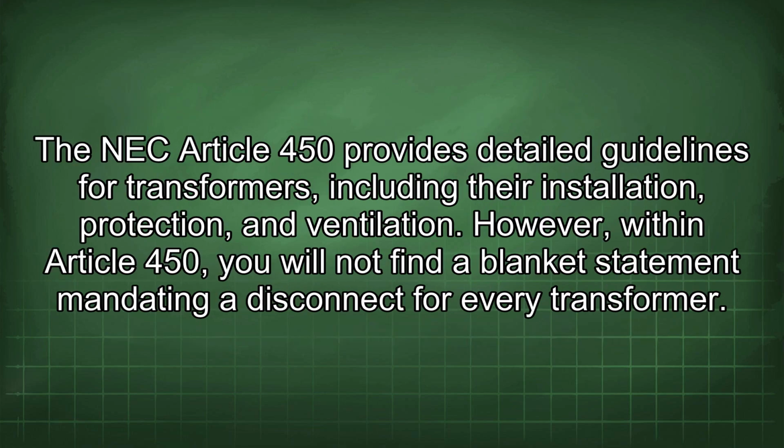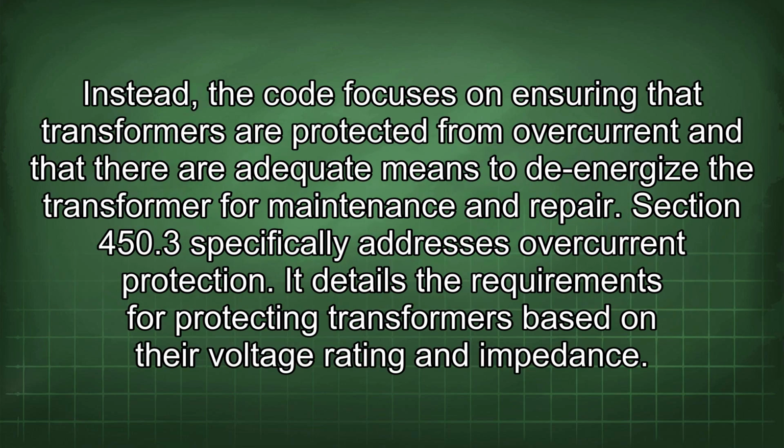NEC Article 450 provides detailed guidelines for transformers, including their installation, protection, and ventilation. However, within Article 450, you will not find a blanket statement mandating a disconnect for every transformer. Instead, the code focuses on ensuring that transformers are protected from overcurrent and that there are adequate means to de-energize the transformer for maintenance and repair.